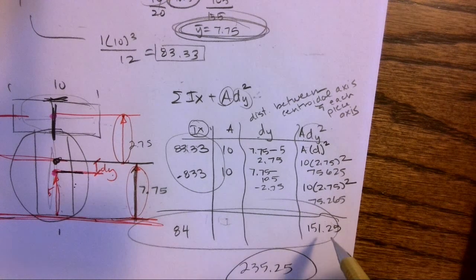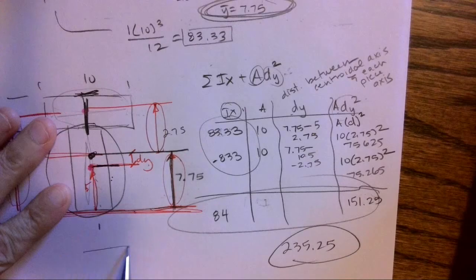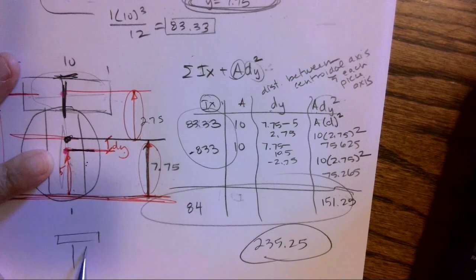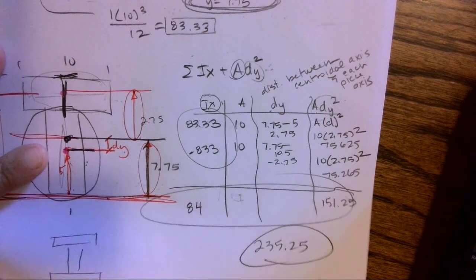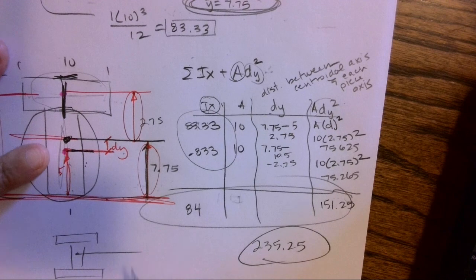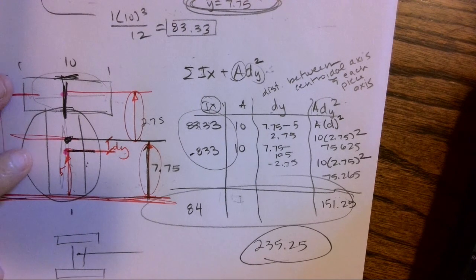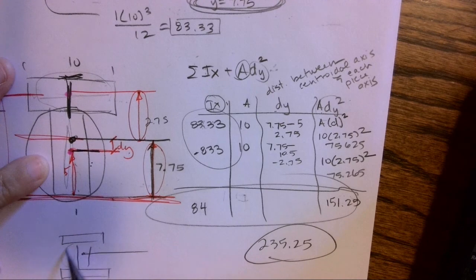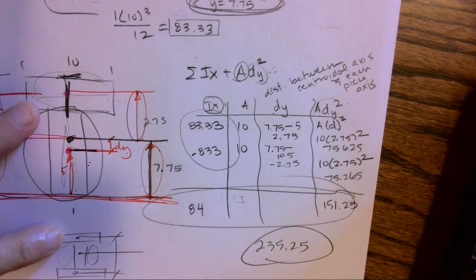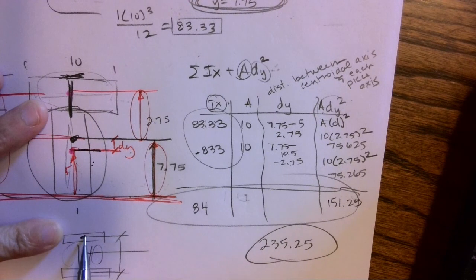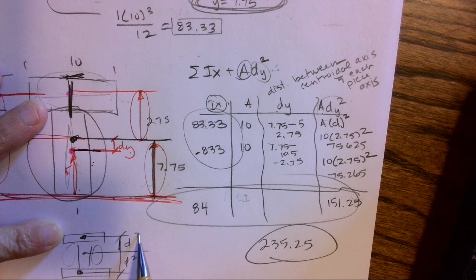So that's the beauty of in steel. The beauty of a W section is that you can decrease the weight, the self weight of a steel beam, for instance, by getting rid of all of this, but you're getting a very high moment of inertia because we are taking the centroidal areas, okay, and we are squaring that distance, and it's really increasing our capacity.